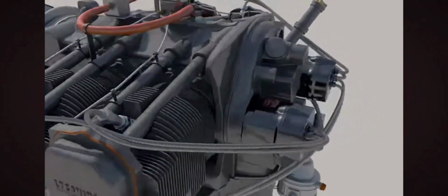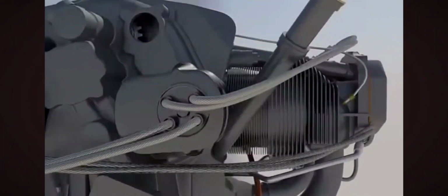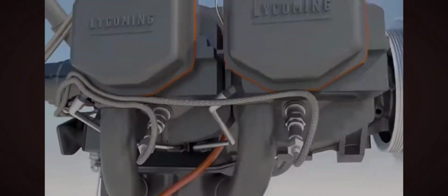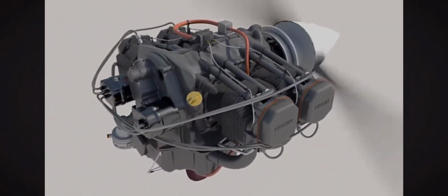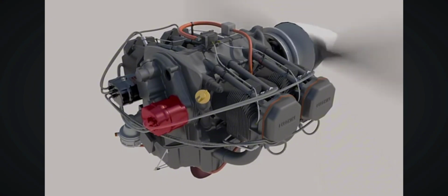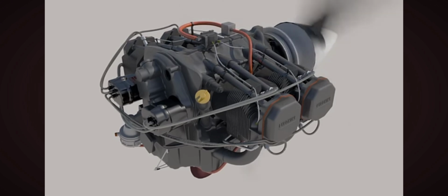Most airplanes have two magnetos, multiple sets of wires, and two spark plugs per cylinder in order to increase efficiency and reliability of the system. If one magneto fails or one spark plug fails, the engine will still run. However, power output will be slightly reduced as the engine is operating less efficiently. The last component is the ignition switch, which is the pilot's way of controlling the magnetos.